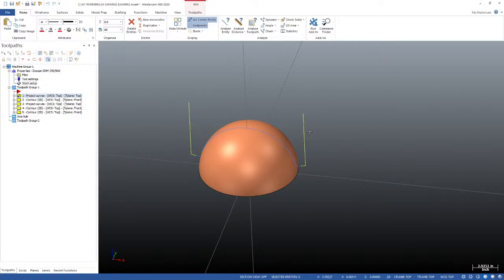And we're going to use some kind of 3D toolpath to machine away the excess material. Now there are some new features that have come out in Mastercam, things like automatic 3+2 roughing, which you can manually adjust to do it in specific ways. Or you might just use regular tool plane based toolpaths and set some depth limits to rough this thing out.